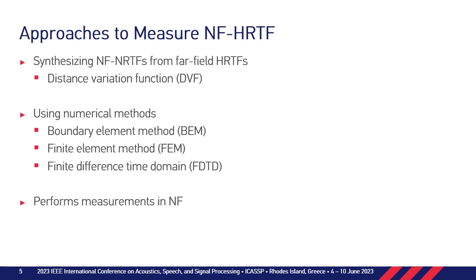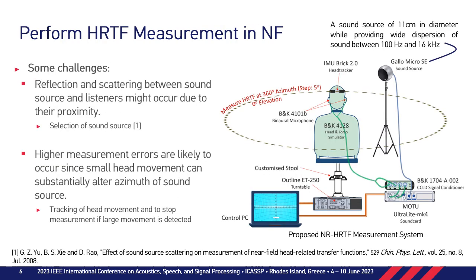The proposed system falls into the third category of approaches, which performs a HRTF measurement in the near field. There are two main challenges in measuring near-field HRTF. At close distances, reflection and scattering between the sound source and the listener might occur. This problem becomes more serious for a multi-sound source system due to multiple reflection and scattering among sound sources.